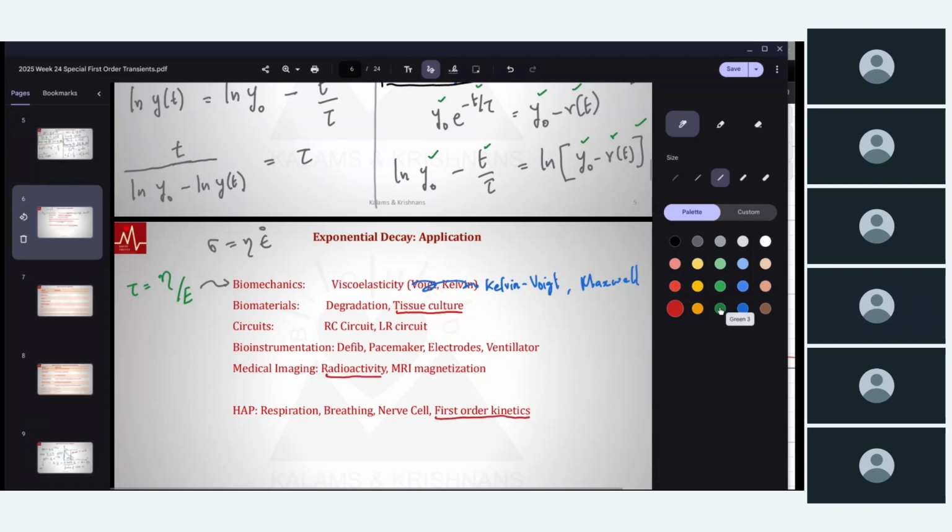In terms of degradation, we're talking about something like weight or density degrading over time. Some of the properties, like composition of a mixture, degrade over time. Density again is changing over time. Strength is not a good way to write it, but let's say strength is decreasing over time. Take a degradable suture, its strength is decreasing. Stretch an aorta, hold it, do an experiment. The force you need to hold it at a stretched position keeps on decreasing. It's getting easier and easier. This is known as stress relaxation. So all those places.